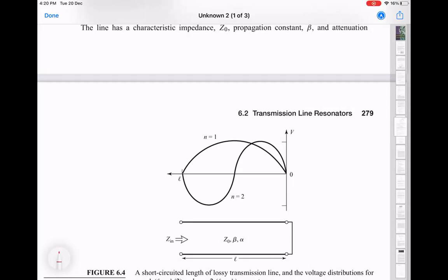But as you go away from the resonant frequency, again, how much away is related to the line width. So if you're within one line width, then everything is okay. If you go much further away, then you will see that the transmission line resonator doesn't match the LC circuit resonator's response as you go away from the resonance.